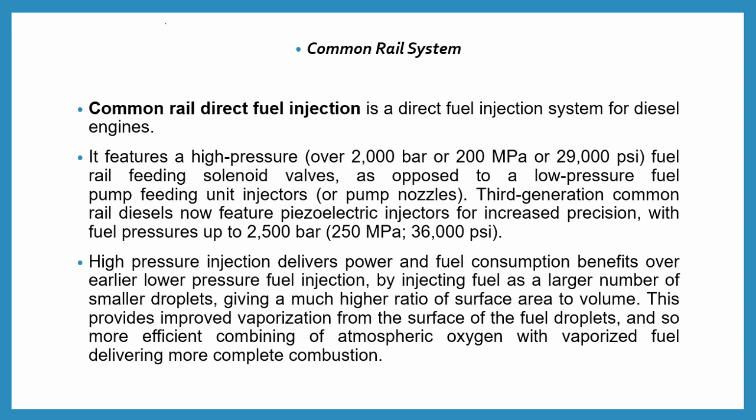So basically when we talk about the common rail system, it features a high pressure, near to 200 megapascal. This pressure in the fuel rail is feeding the solenoid valve, as opposed to the lower pressure fuel pump feeding the unit injector.